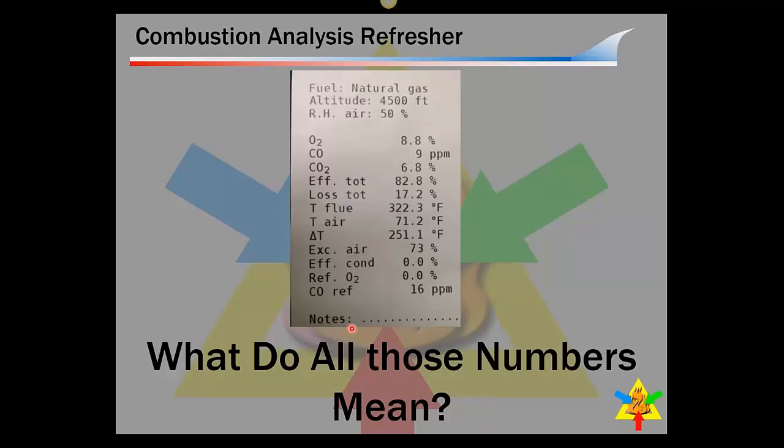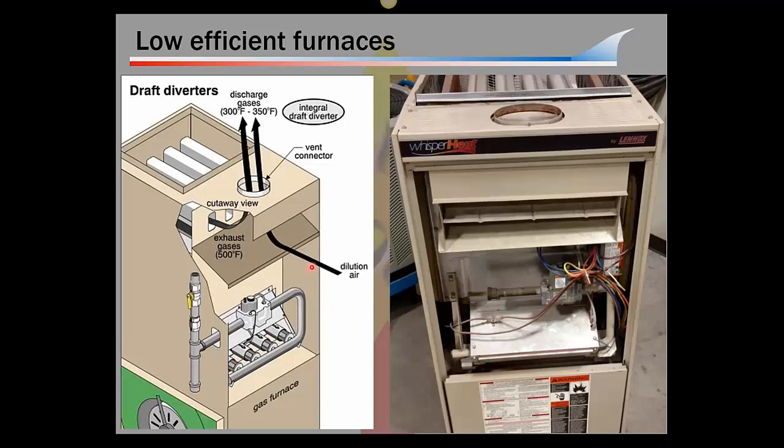Hey Wade, on that one, do you average them when you're done, or do you want to report and kind of put in your file the CO from each burner? You would just take the CO from each burner, and again, I'd go back to my example. If we measured all 4 of these, and let's pretend that this one was 400 parts per million, and the other 3 were 20, 15, and 10, we have a problem. Document them all, but your problem is right here.